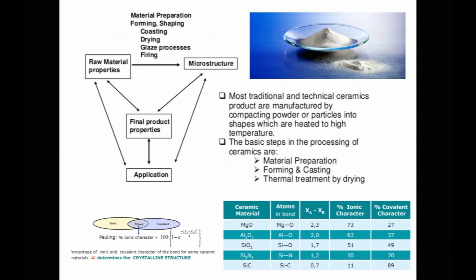How do we form them, or industrially, how are ceramics processed? Well, other than the mineral materials that are derived from clay, the ground, or mined, if we have a powder that represents different types of oxide and non-oxide compositions, they are usually best processed initially as powders or particles that can be created into shapes or held into shapes by a binder material and then heated to high temperatures.